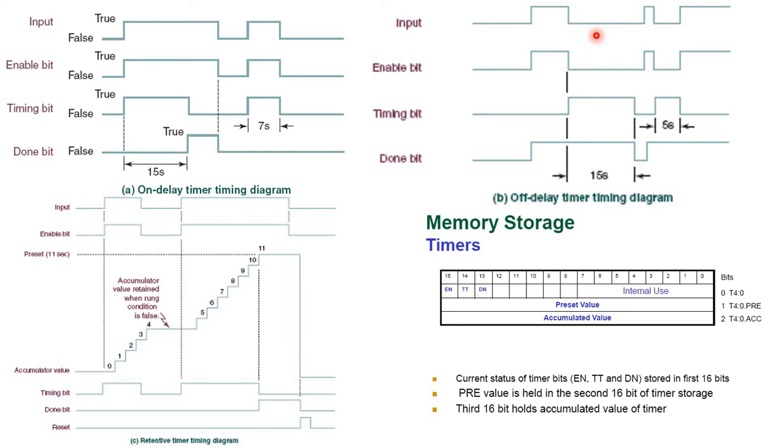Okay, the TOFF timer is a little bit different, unique in nature. The purpose of using a TOFF timer is that you turn off a main device, but still you want to keep your sub device, another auxiliary device, activated until a certain time has lapsed. So I repeat, you turn off your main device, but you still want one of your auxiliary devices to stay activated until a certain time has passed.